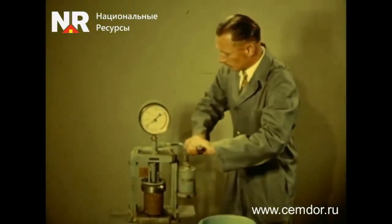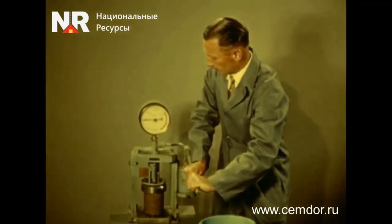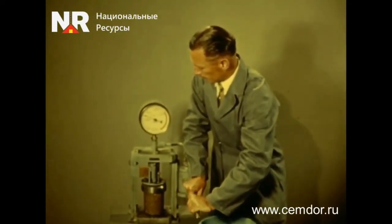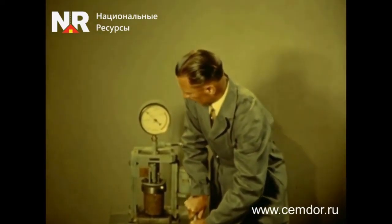In practice, the strength characteristics of soil cement are the basis for calculating the entire pavement structure. At the same time, low soil strength may indicate the presence of various impurities in the original soil, which hinder the hydration of cement.